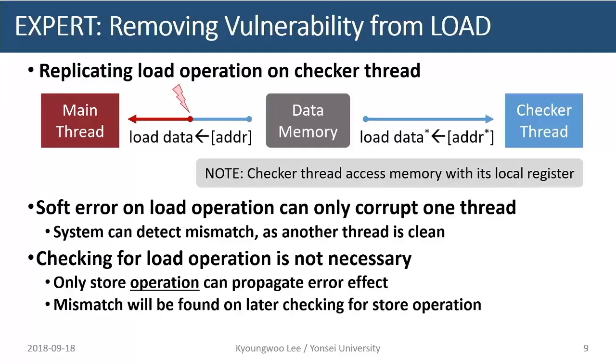Actually, checking for load operation is not necessary because it does not propagate incorrect data into data memory. In other words, only a store operation can put the corrupted data into the memory. So this mismatch can be found by the later checking for the store operation.